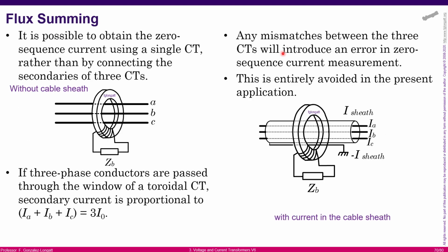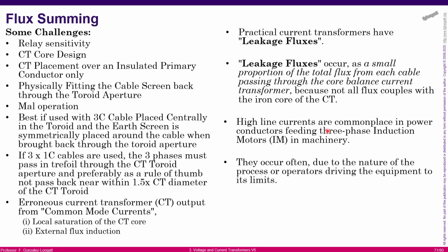Again, this can be used for relatively medium low voltage applications. It's quite useful if you are working with induction motors. This kind of approach is quite used in order that you can see some imbalance in the machine and any kind of phenomenon with asymmetrical components. Okay, well, it's good that you have a reading about flux summing, and I would like to say that at this moment we are finishing the part related to current transformers.